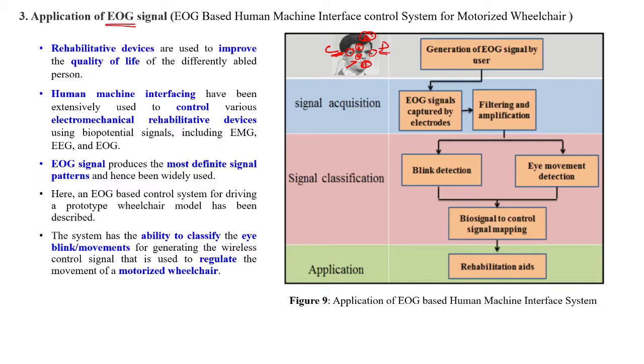There are other ways. Suppose you want to find out at this location, then both C and A would give you some reading. Also, if you move your eyes towards the nose, then the B and D electrodes will also give some reading. So you have vertical signals and horizontal signals.